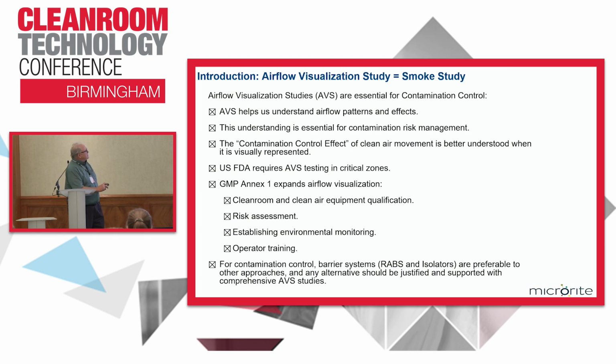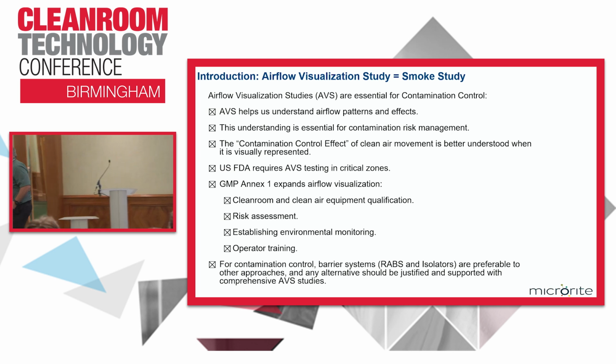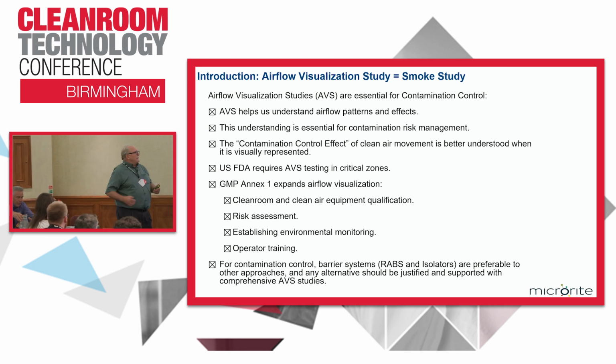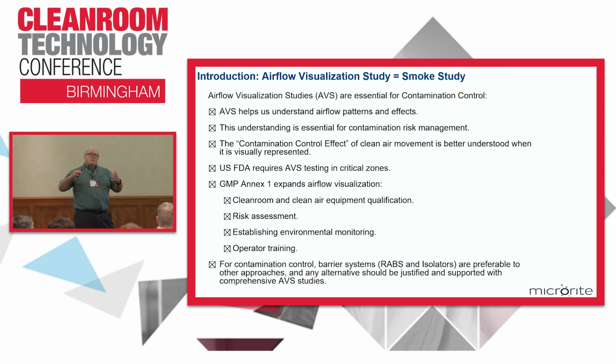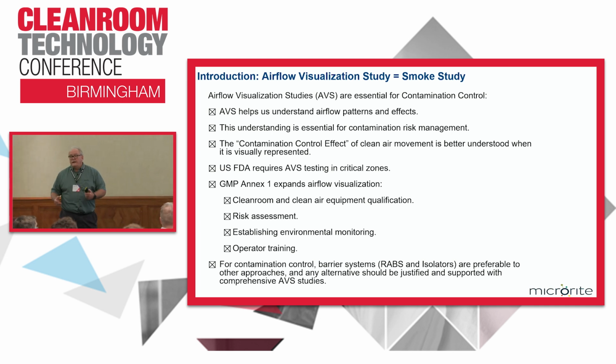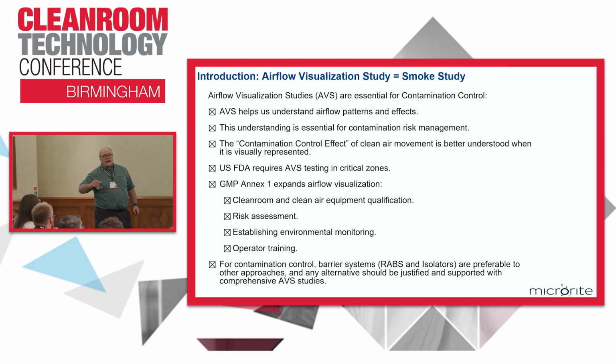And the contamination control effect, a phrase I like to use often because it really describes this, when we talk about airflow, is that how air moves in a cleanroom is essential. What's the difference between an ISO Class 1 cleanroom and an ISO Class 9 cleanroom? Design considerations, but number one is how air moves.